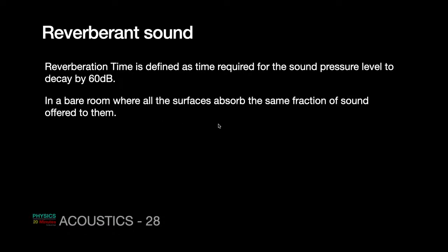In a bare room where all the surfaces absorb the same fraction of sound offered to them, the reverberation time is a constant into volume upon area. Now, remember, important criteria is here. You figure out the volume, figure out the area, calculate the reverberation time, but all the surfaces must absorb the same fraction of the sound for this formula to apply. That means all the surfaces must be similar or same.